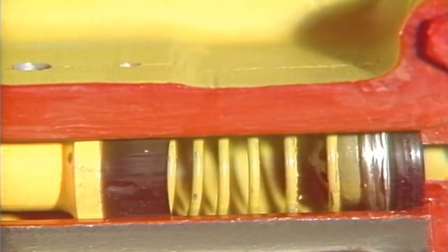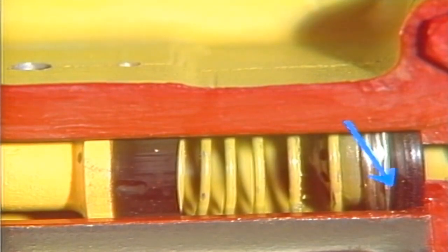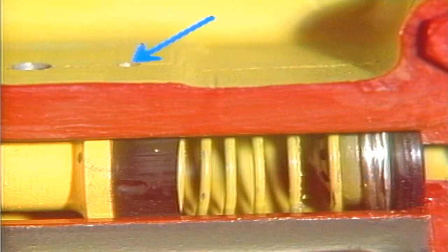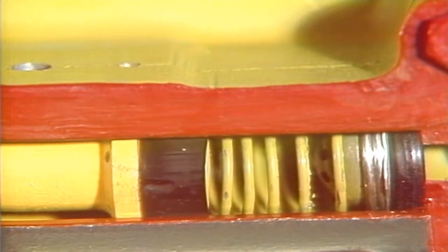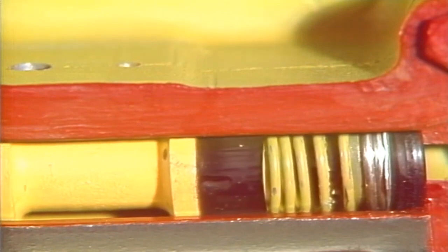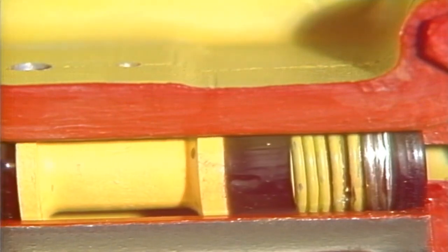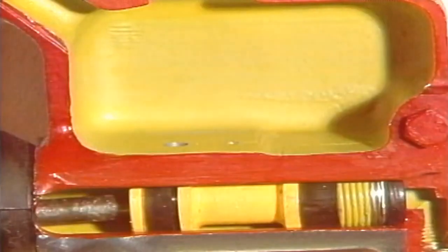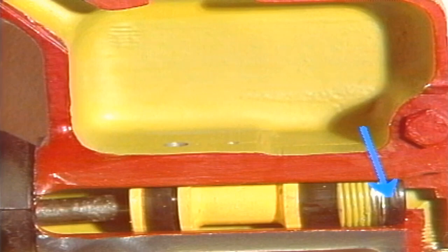As the push rod transmits pedal motion, the spring applies force against the residual pressure valve, while at the same time the piston cup closes the compensating port. This primary cup faces forward, and as piston motion continues, it seals in the pressure that now starts building up in the outlet end of the cylinder. This fluid pressure unseats the residual pressure valve, opening the way for the brake fluid to pressurize the brake lines and wheel cylinders. We'll look at what happens there in a moment. For now, let's follow the action in the cylinder when the brake pedal is released.